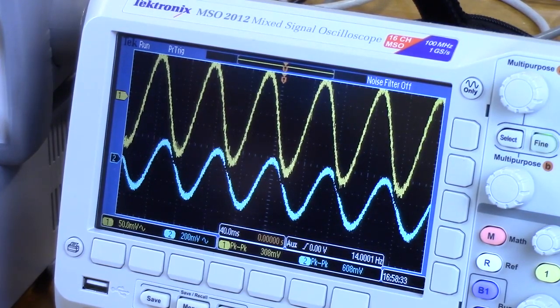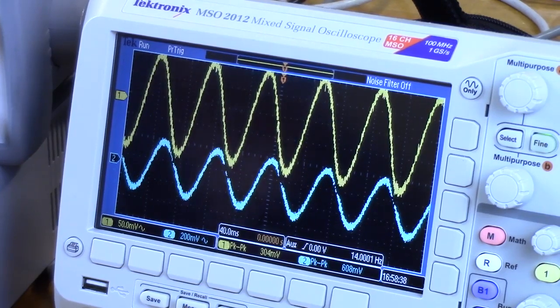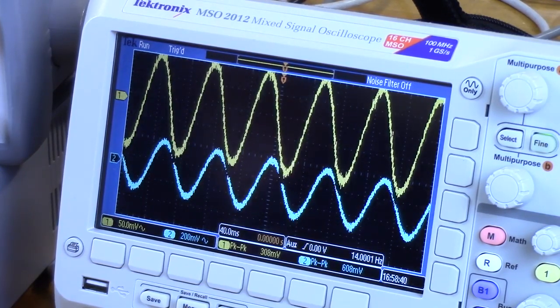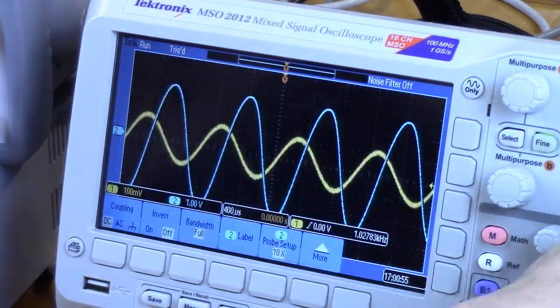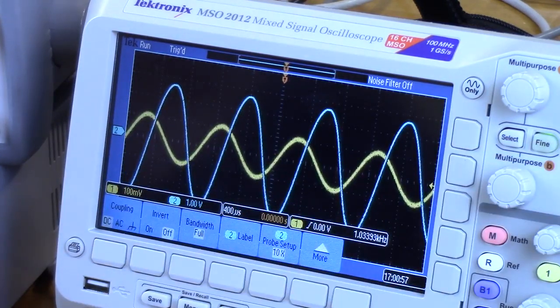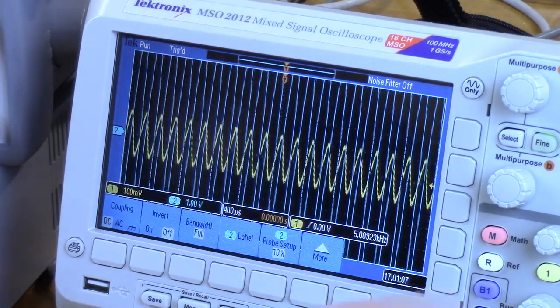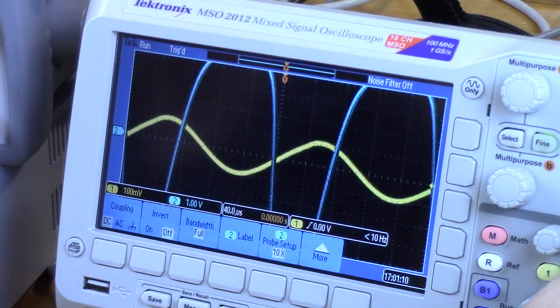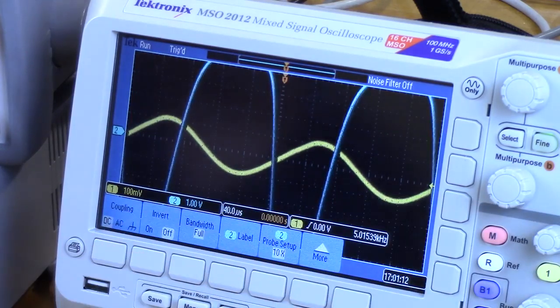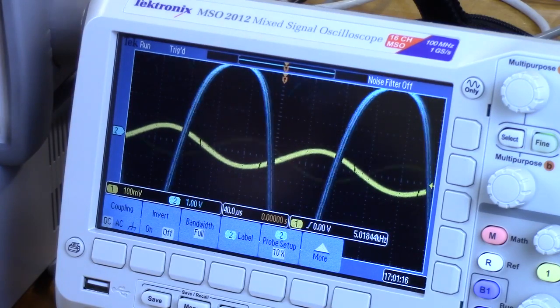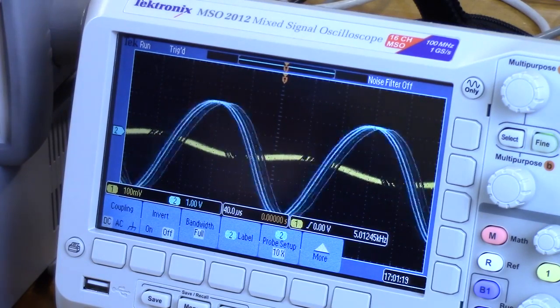All right, so now to look at C2, what we're going to do is let's move C1 and CE out of the way. So I still don't really like this display. Okay, so I think we're kind of back where we're supposed to be, except this looks nothing like, oh, it's at 1 kilohertz, okay. All right, so let's go back to 5 kilohertz. See if we can get into mid-band condition. And it looks like we are, but we're overdriving, so amplitude. Let's get it out of the point where it's clipping.